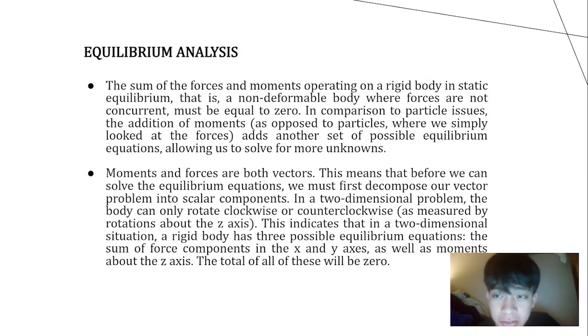Equilibrium analysis. The sum of the forces and moments operating on a rigid body in static equilibrium, that is, a non-deformable body where forces are not concurrent, must be equal to zero. In comparison to particle problems, the addition of moments gives another set of possible equilibrium equations, allowing us to solve for more unknowns.